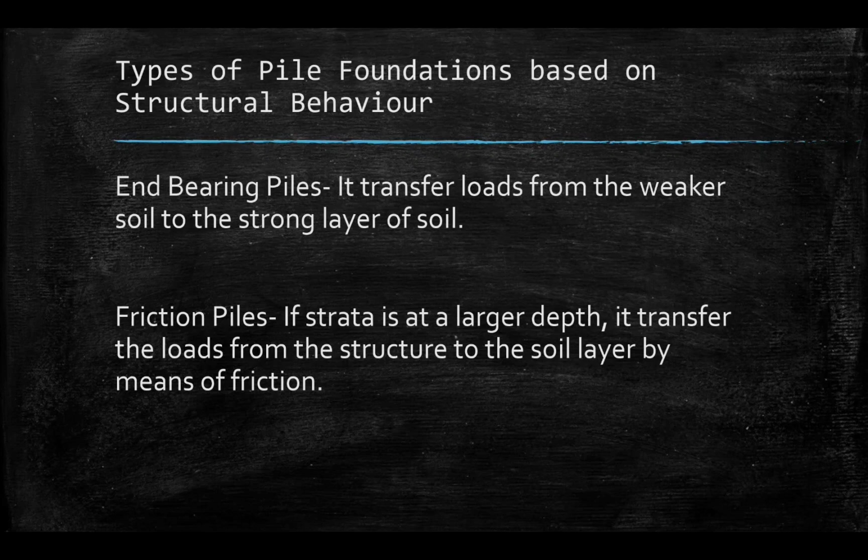So, paano naman natin ngayon i-increase ang frictional capacity ng ating pile? To increase the friction capacity of the pile, we have to also increase the roughness of the pile since nagre-rely yan sa the friction between the surface of the pile and the surrounding soils. So, increasing the roughness of the pile, increasing the diameter, increasing the pile length, and of course, increasing the number of piles. Okay?